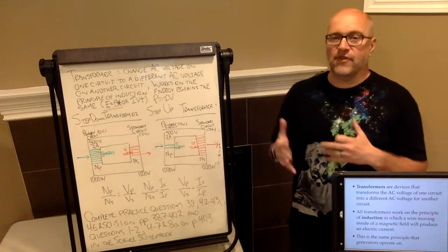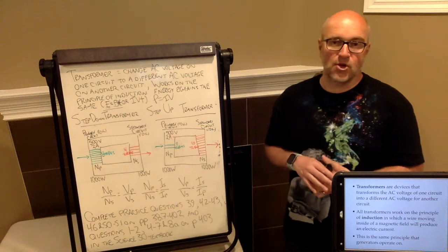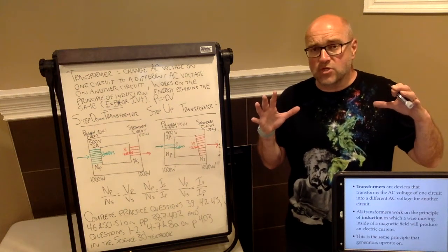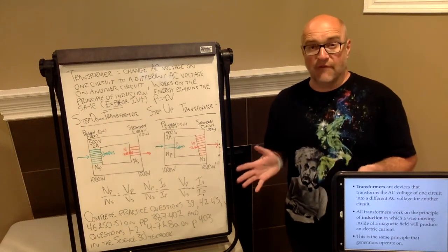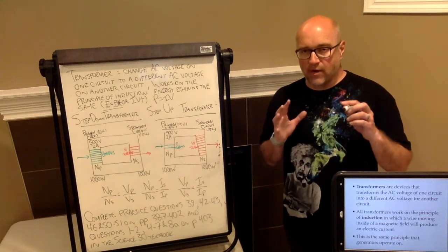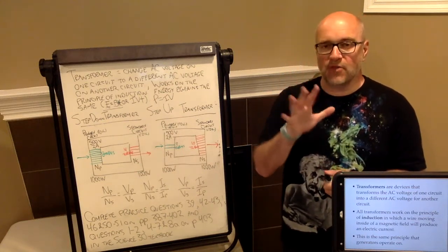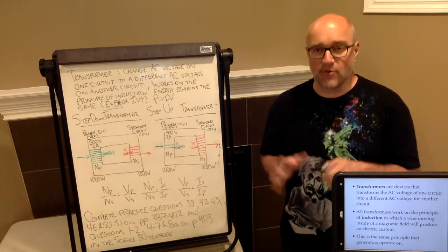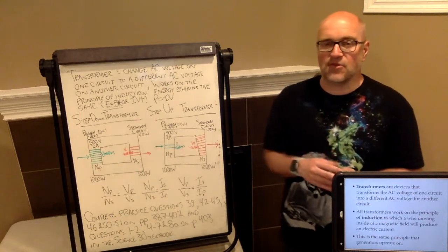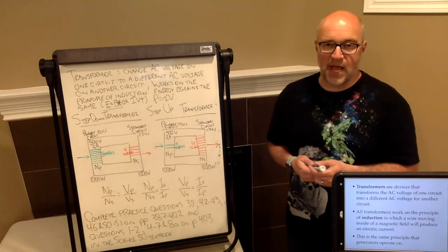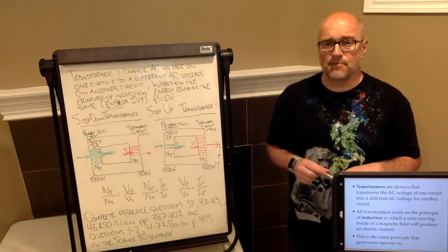Some of it, more of it becomes either voltage or current, depending on what the transformer is doing. Now, like I said, when we're distributing electricity down the line through transmission, we want high voltage and very low current, because with not much current in the line, there's not as much of a problem with resistance. Remember, resistance is kind of trying to stop current. Resistance doesn't really affect voltage per se. So if I have high voltage and low current, that's a great way to transmit electricity.